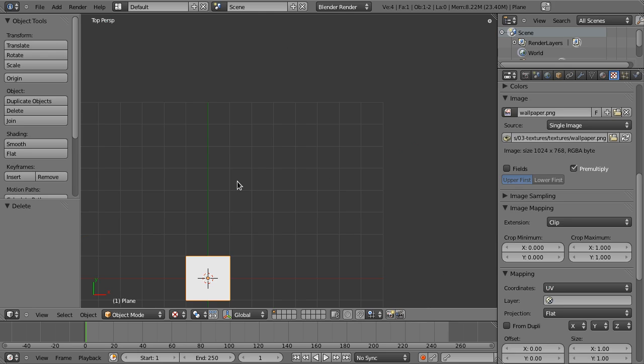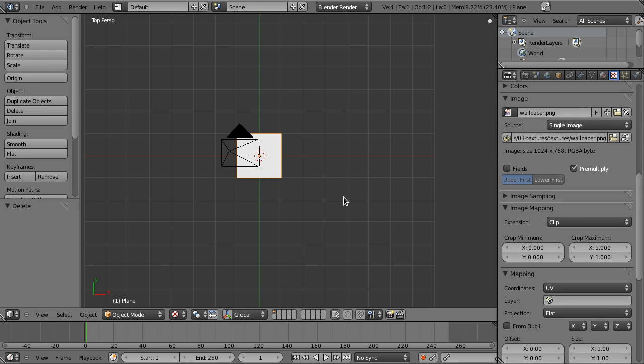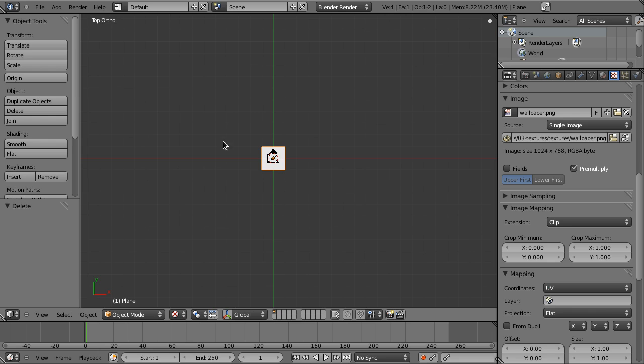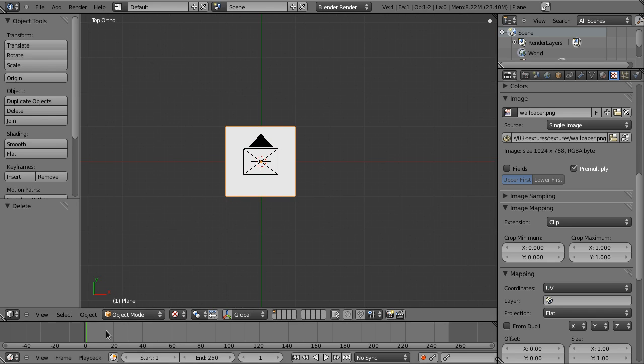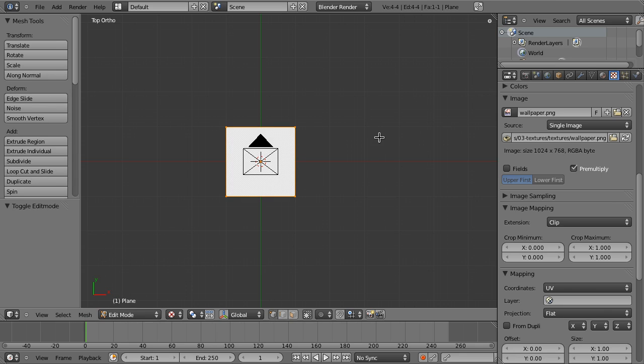And to do the UV mapping, we actually have to talk about the edit mode. So by default, Blender is in the object mode, and we did marvelous things like transformations, rotation, scaling, and movement. But if we enter something called the edit mode, we go a level deeper in the object hierarchy. So in our case, we're working with meshes.